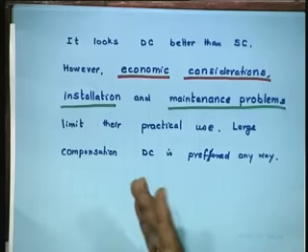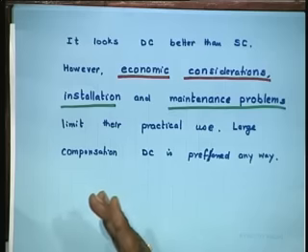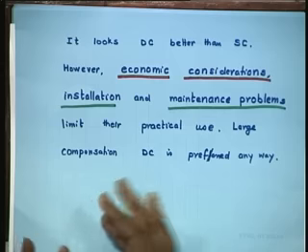So, this is a dynamic compensator, which means rotation is involved. So, maintenance cost will be more as compared to static equipment. Similarly, installation cost will be more in case of a synchronous machine. In a capacitor and bank of inductors, what is the installation cost? Further, we do not know where we need this compensation. Where are the loads? The industry can be anywhere, the load can be anywhere.